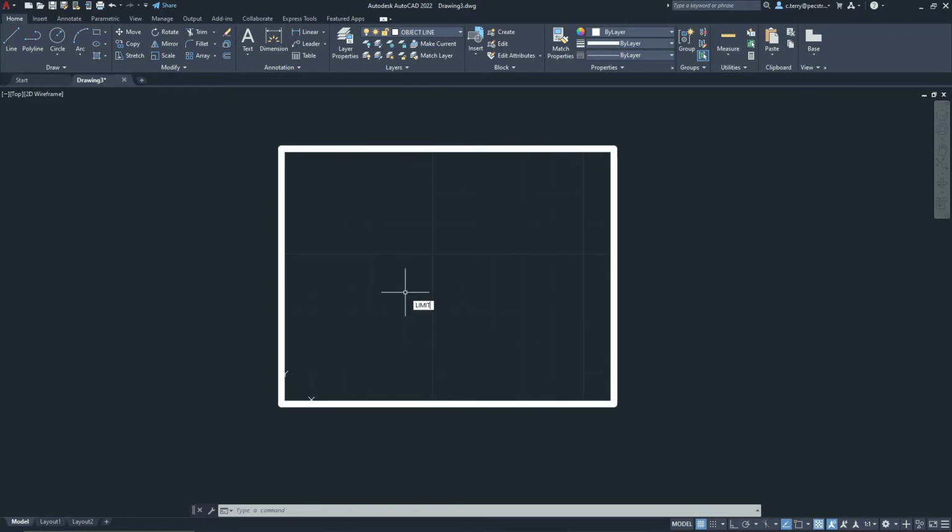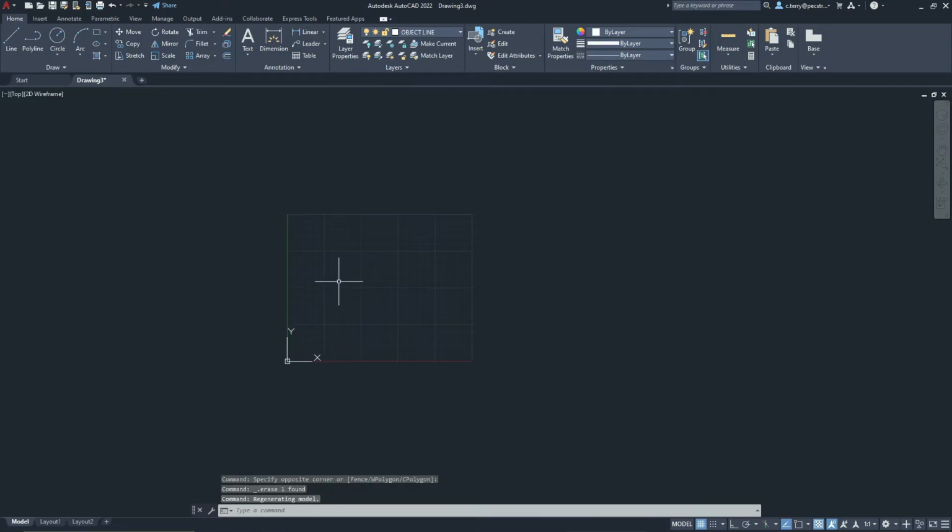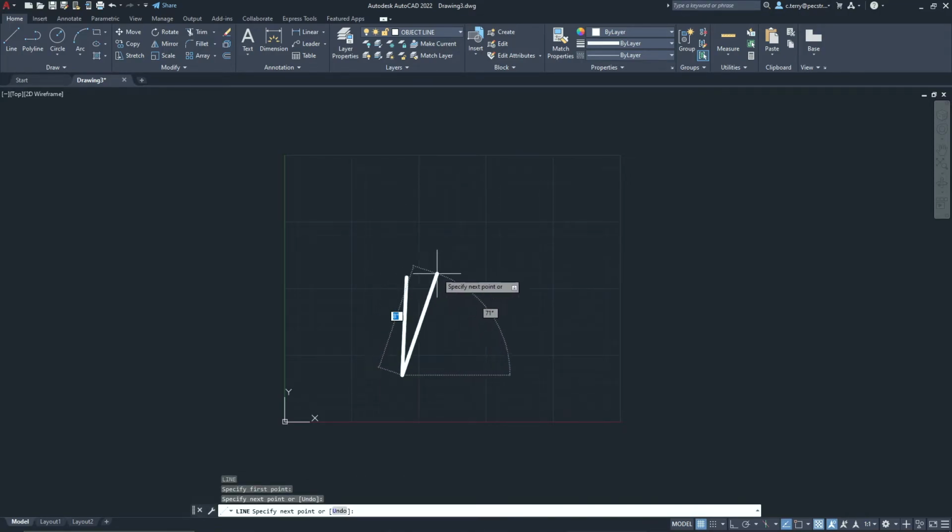So then we need to set the limits for the drawing. We're going to do 0, 0 to 2520. And delete this. So it'll be different for each one, so make sure you do this. Your instructor will probably be checking to make sure that you've actually done this. Make sure you do your zoom all to check everything. Make sure you're good. Erase the rectangle. Turn off the snap and the ortho. So we're going to hit, let's see, yeah, all that's off already from the last time.